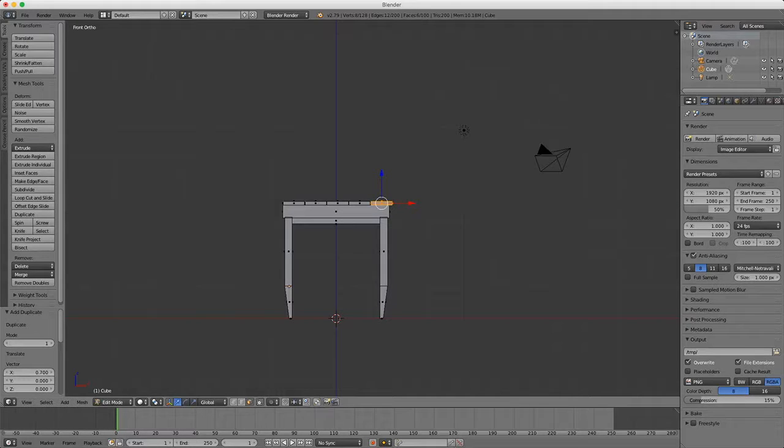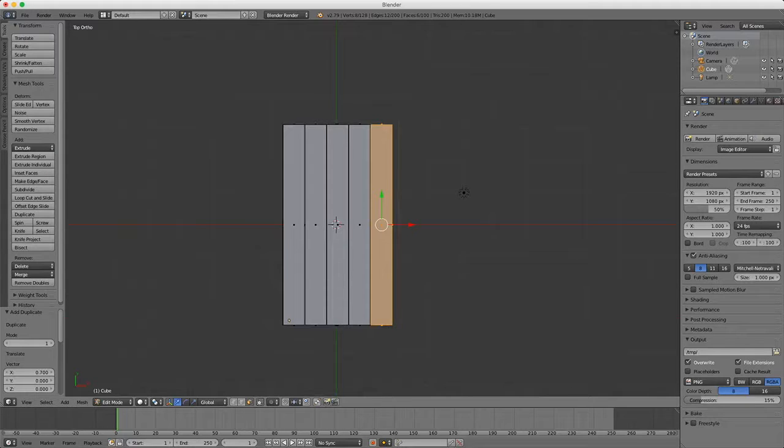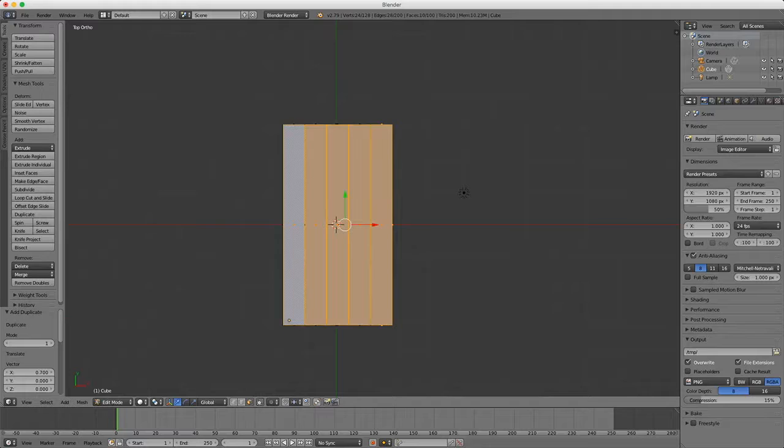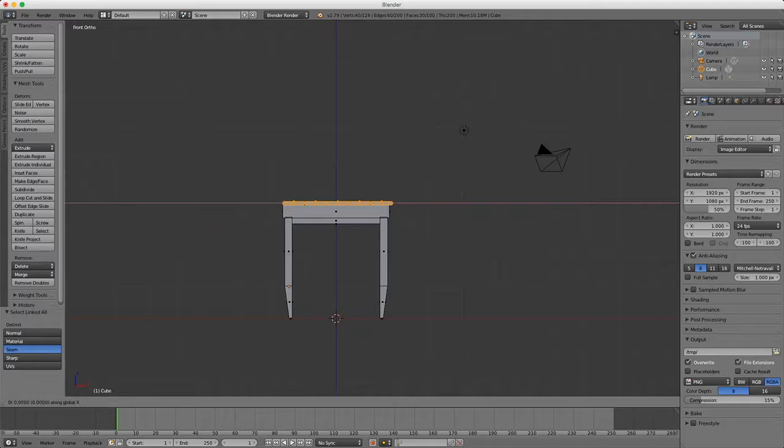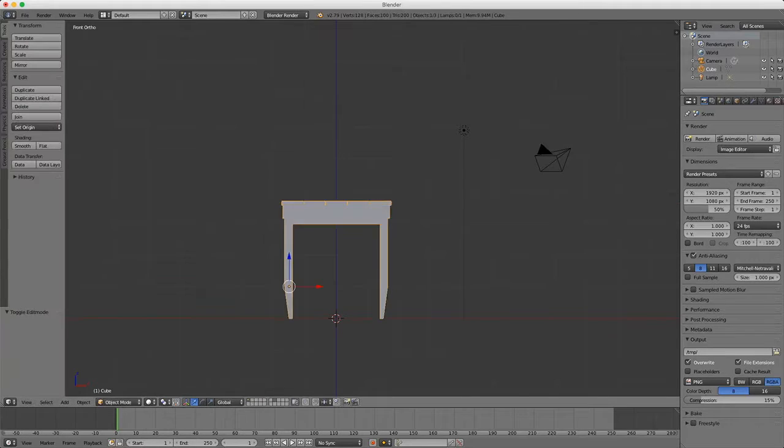Now, press 7, for the top view. Hold Shift and right-click the top face of the remaining unselected 4 wood planks. Press 1 for the front view. Press Ctrl, L, to add the remaining faces of each plank to the selection. Press G, X, -0.04, to move the planks 0.04 units to the left along the x-axis. This will make the distribution look a bit more polished. Press Enter. Press Tab, for object mode.